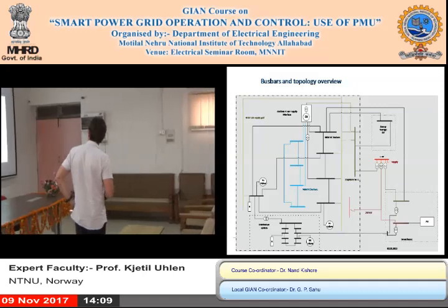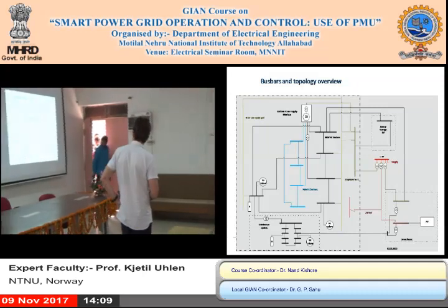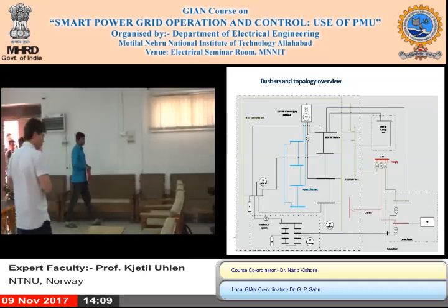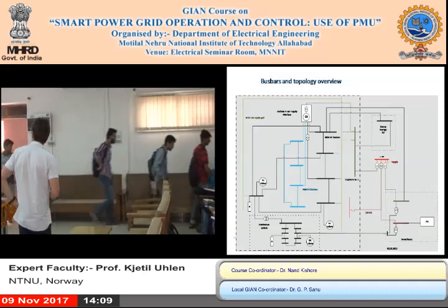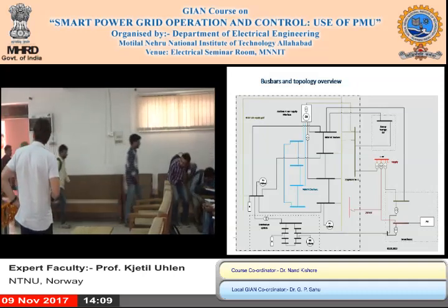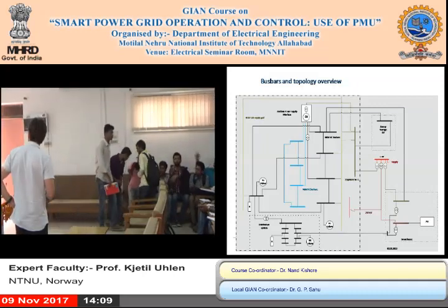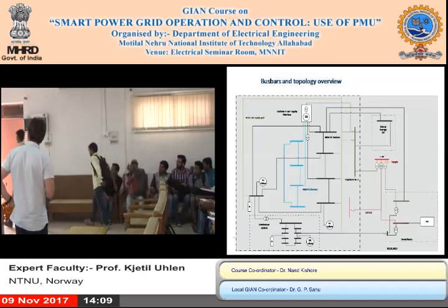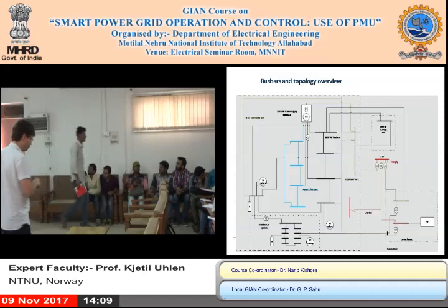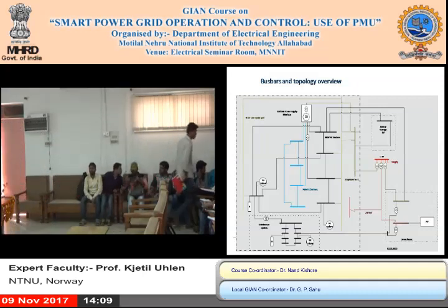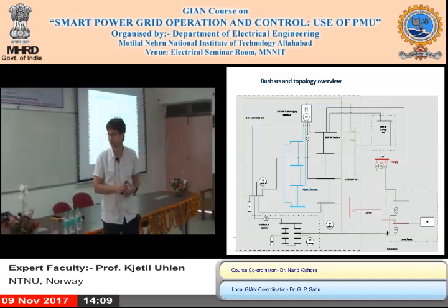And to these bus bars, there are some permanently connected machines or drives, so that we can simulate power plants, and there are loads, and there are converters, and there is a controllable power supply here of 200 kVA for us to make also a real-time simulation which can be connected to the hardware.